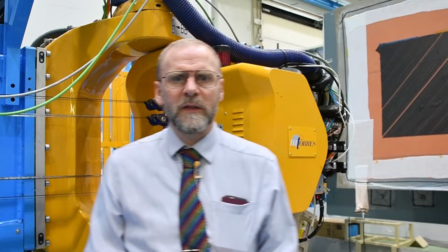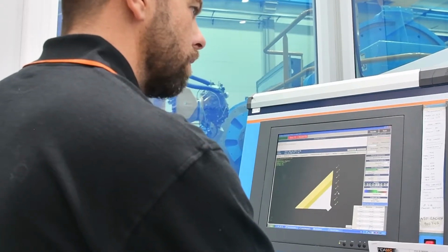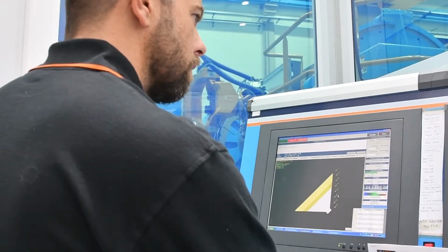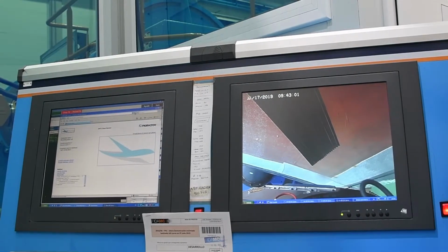The ZAero partners supplying the measurement capability can write to the MDB the actual fiber directions, thickness, and anomalous features detected during layup. The features can be characterized as special types of defects. Information about the model stored in the MDB can guide the systems in how the measurement data should be stored.